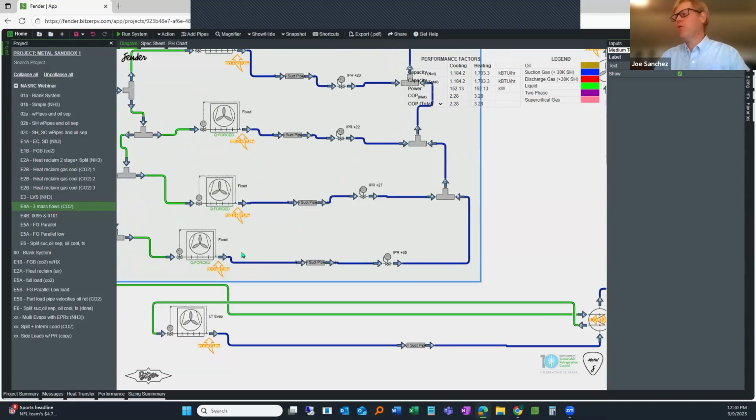So if you know CAD, then when you're doing hand sketches, you have to define your sketch and your assemblies in a very particular way so that it's exactly constrained the right way. If you're drawing a square, you can't dimension every single line and also say that every side of the square is equal to each other, because now you have two constraints that the computer is trying to deal with. So that's kind of similar here.